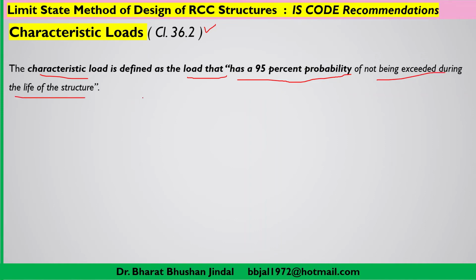So as per the definition, the characteristic load will be that load which has a 95% possibility that it will not be exceeded during the life of the structure. That load will be taken into consideration for calculation purposes, and that will be termed the characteristic load.